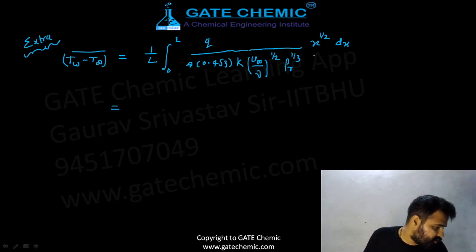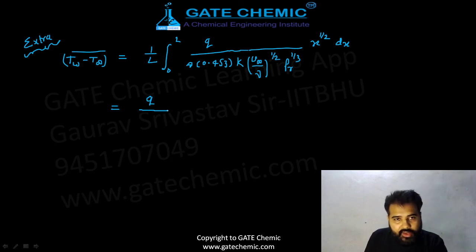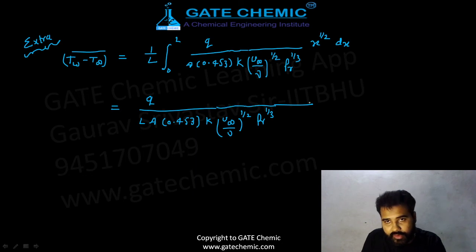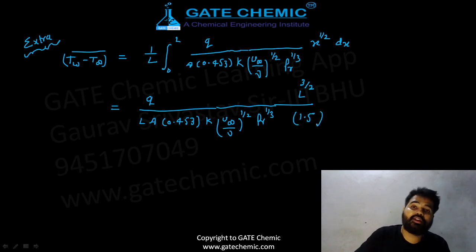It can be written as q equals h L into A into 0.453 into K into u infinite by nu to the power 1 by 2, Prandtl number to the power 1 by 3, and here you can write L to the power 3 by 2, that means 1.5 by 1.5. If you want, you can write 1.5, it will look better. Write 1.5 in place of 3 by 2.